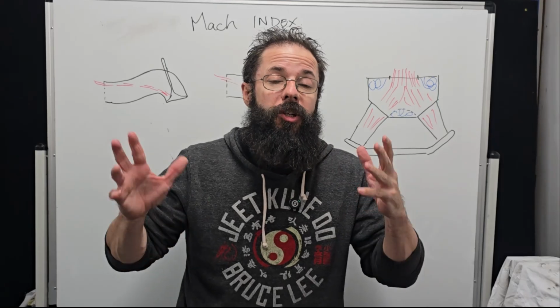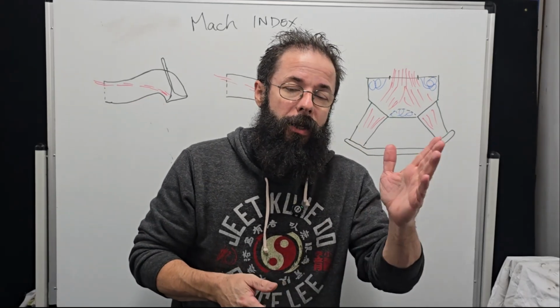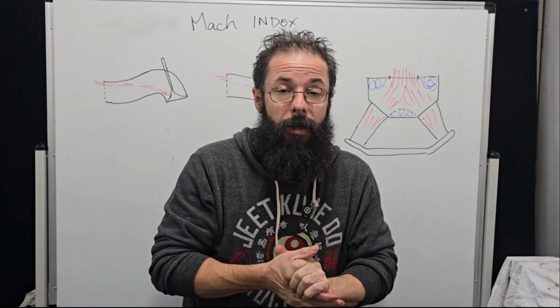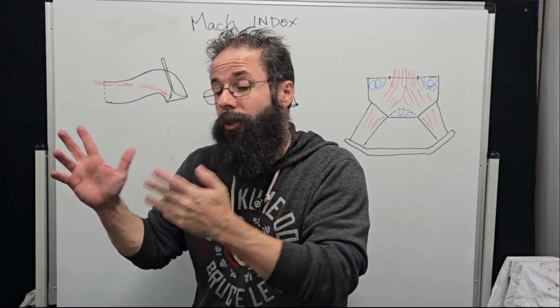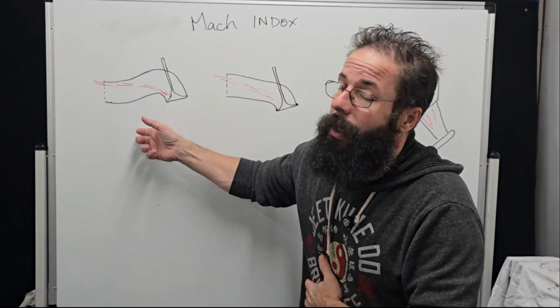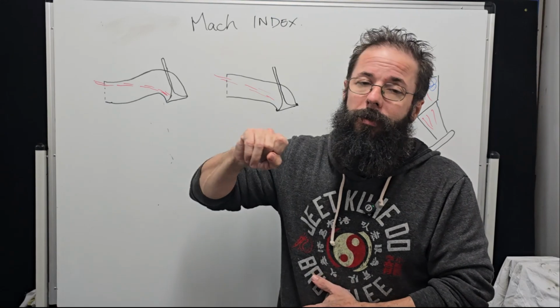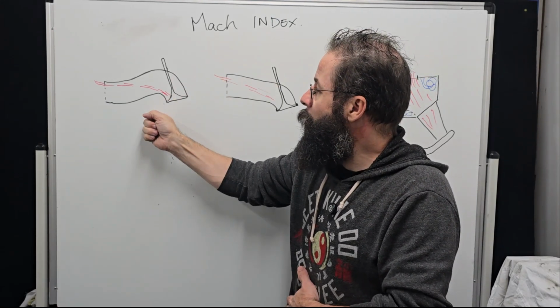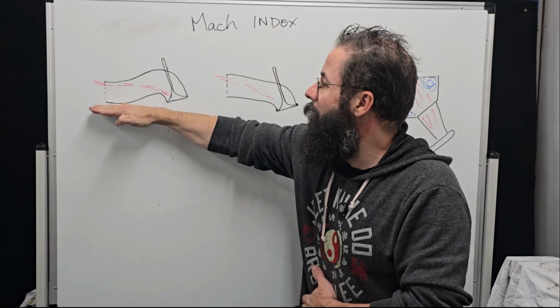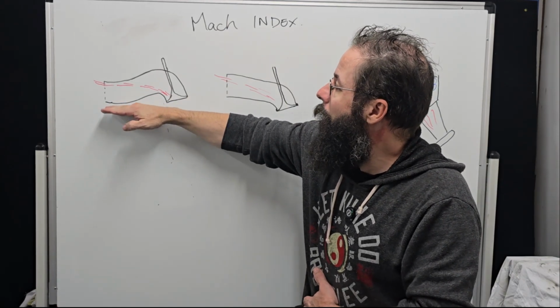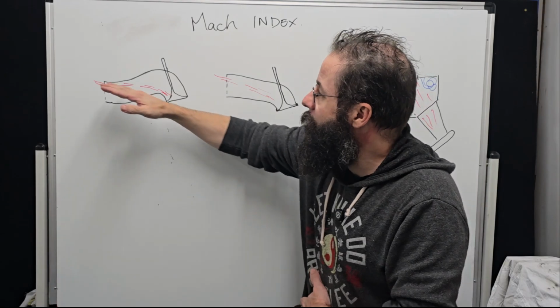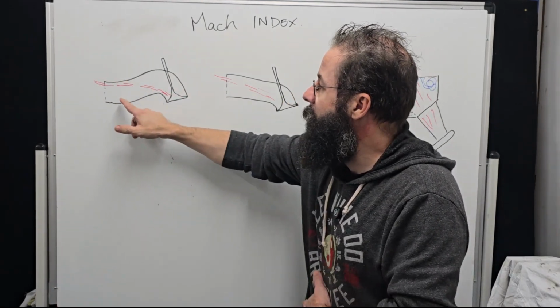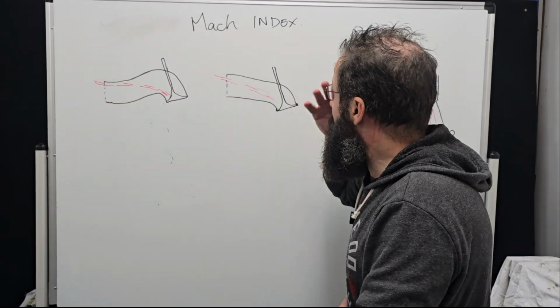All right, again, I'll just finish up on the Mach index, and then we'll cover some other topics that were brought up. So I just thought I'd demo just quickly. This is what I was talking about when I was talking about high and low, because a lot of people don't understand it. 23 degree, as you can see, really, really low port window. The air's got to come up and go down. So we'll definitely get this velocity gradient. Again, really, really dead floor.